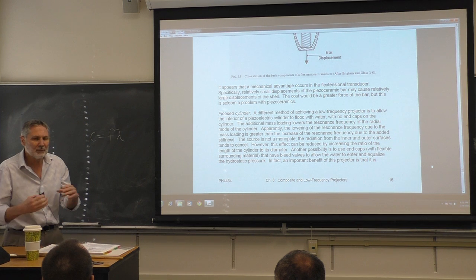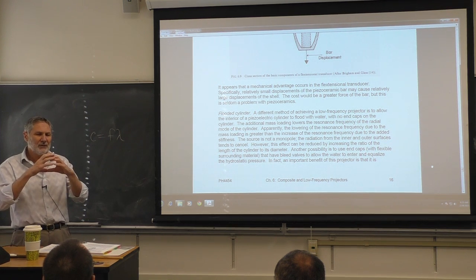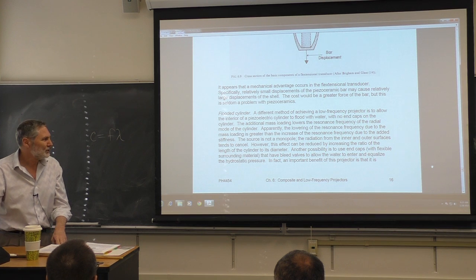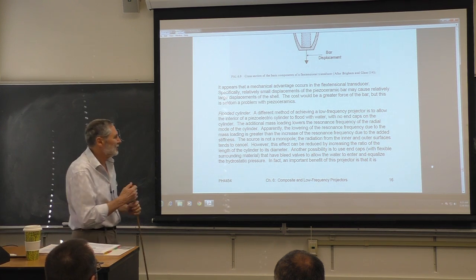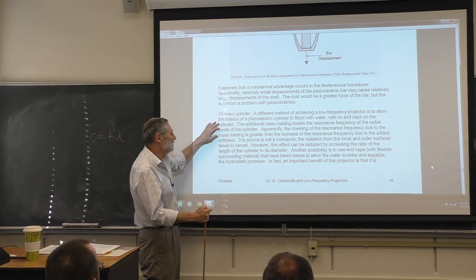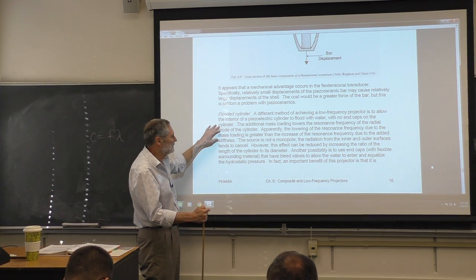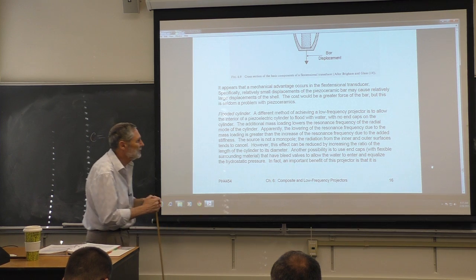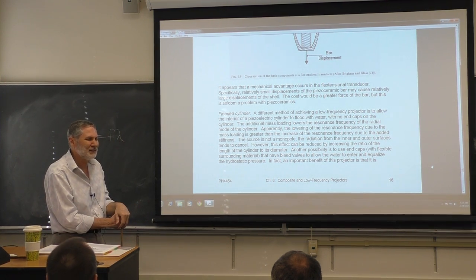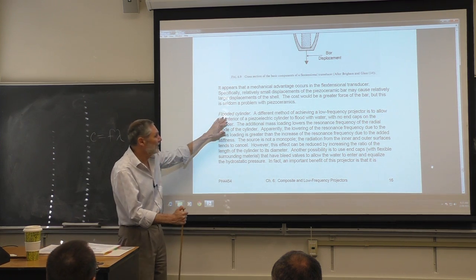The idea is that by putting water in there, we've increased the inertia and we can lower the resonant frequency. However, we've increased the stiffness, right? Brian doesn't talk about that, and I couldn't get deeply into these papers. It takes too much time. But anyway, apparently, the added inertia beats out the added stiffness. I'm suspicious about that, but this is commonly done.